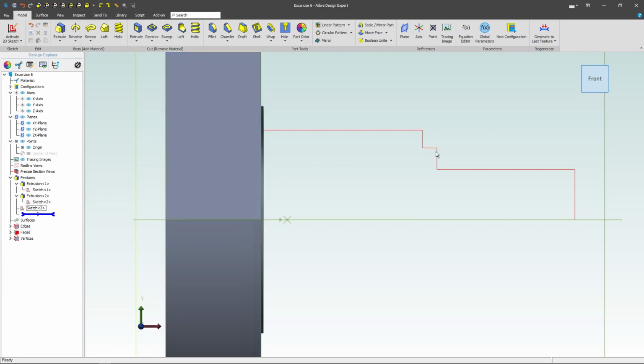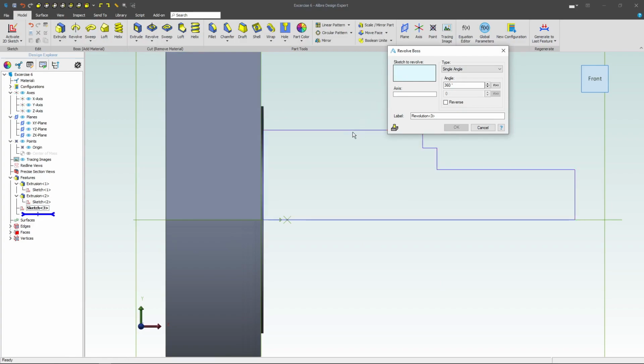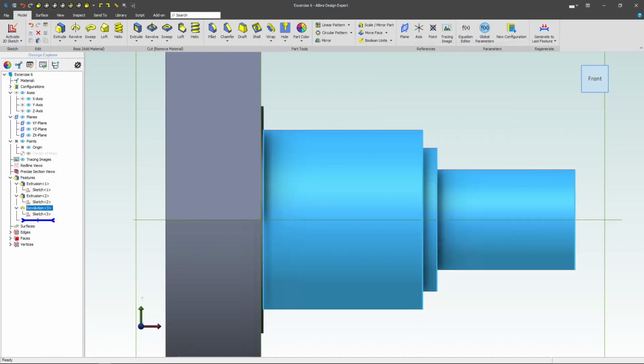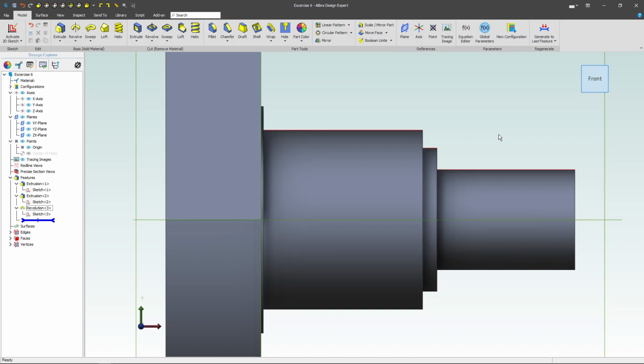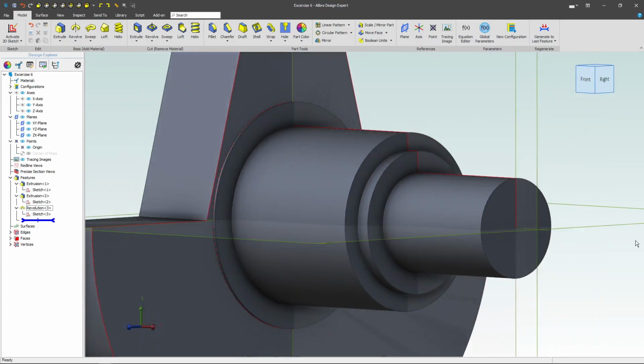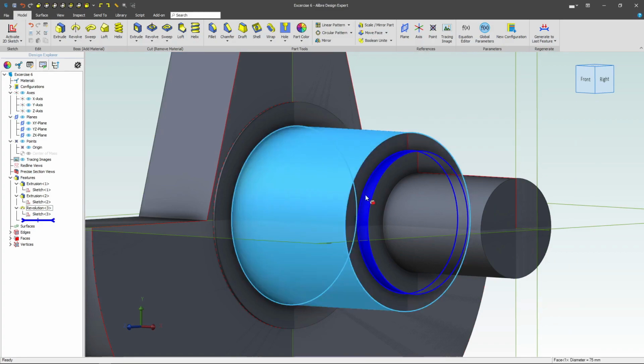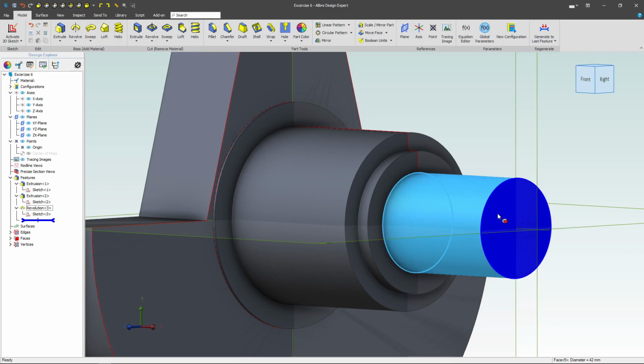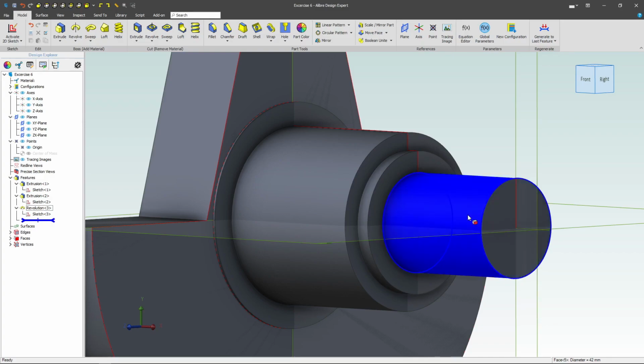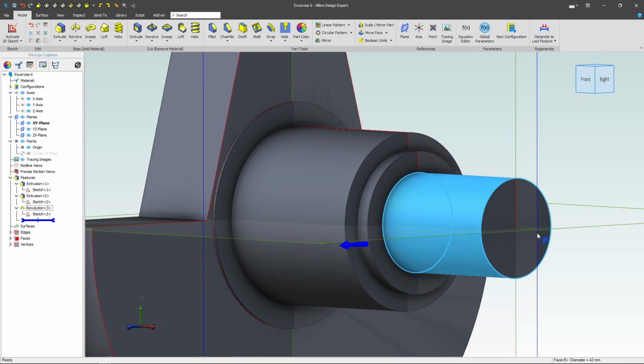We'll deactivate the sketch, and now we'll revolve. We'll select our sketch and our axis here, and that's our revolution. Next thing, I should talk about design intent. I did this in a revolve, but you could also extrude this face, extrude this face, extrude this face in 3 separate extrusions. So it all depends on, do you want to update sketches or extrusions? And each would have their pros and cons depending on what your needs are as the designer.